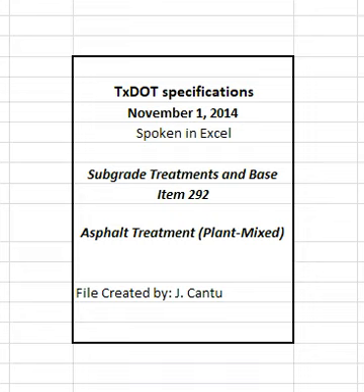The aging ratio, as determined in accordance with TxDOT 315, is the DSR value of the extracted binder divided by the DSR value of the original unaged binder. The binder from RAP will be included proportionally as part of the original unaged binder. The engineer may require the defective material be removed and replaced at the contractor's expense. The asphalt binder will be recovered for testing from cores in accordance with TEX 211F.